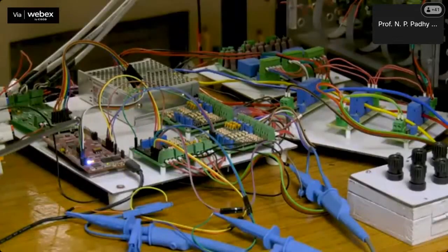These input signals are given to the programmed control system in the DSP controller, which generates the required PWM pulses. Here the DSP generates PWM pulses at a voltage range of 5 volt. The switching voltage range of the IGBT present in the Semikron stack is around 12 to 18 volts. The generated 5 volt PWM pulses alone are not sufficient to drive the IGBT switches.